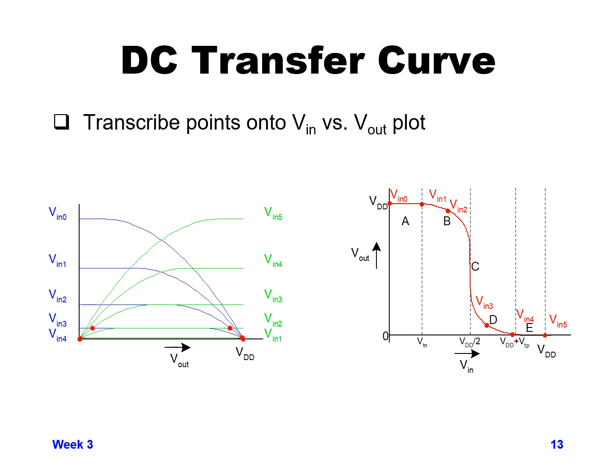And then when we get to 3, 4, and 5, we have an output voltage that gets pretty close to ground and stays pretty close to ground most of the time. And it's only when we get to that voltage that's exactly halfway between VDD and ground that we have a really fast switch of Vout between VDD and ground.